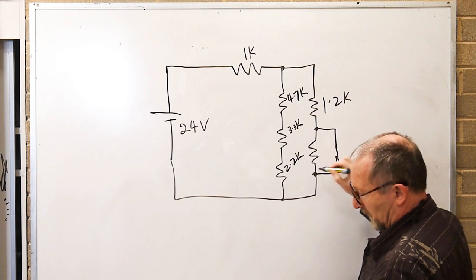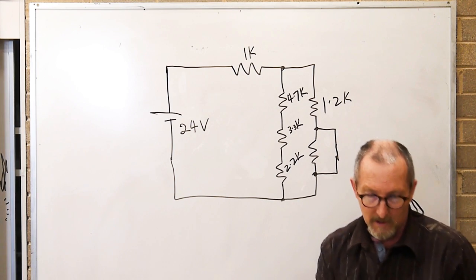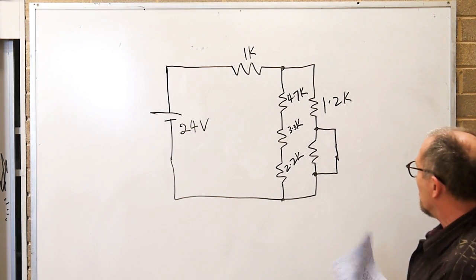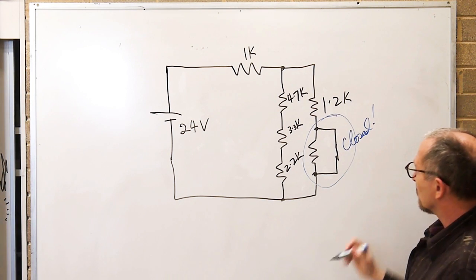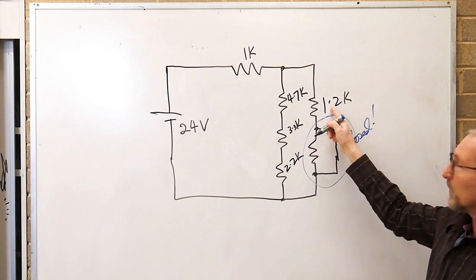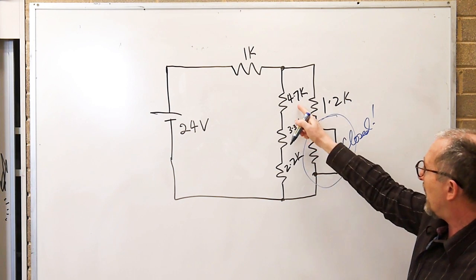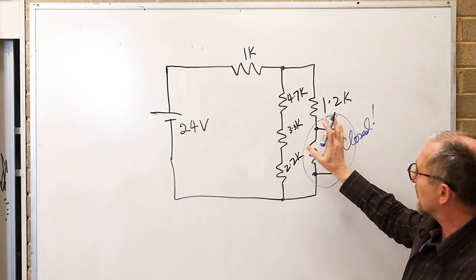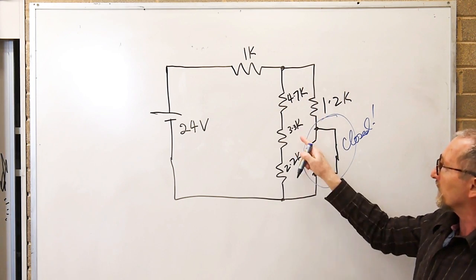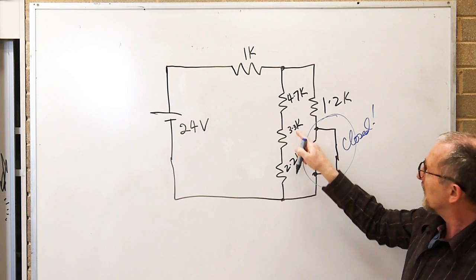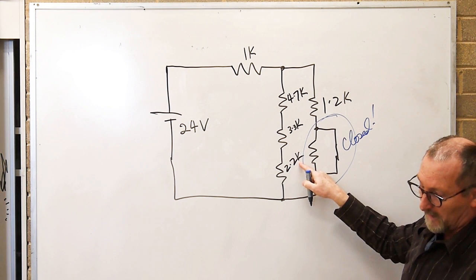across this resistance here. One of the first things I did on my approximation circuit, I got a pen and I circled that and I just went closed like that. So then I know I'm only working with 1.2K. Just remind myself what I've got in front of me. And then adding these up, because I know that I've got a series parallel circuit here to work with. So 4.7K, 3.3K, what have we got? 7, 8K, 10.2K is it?